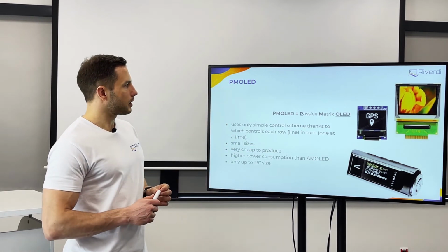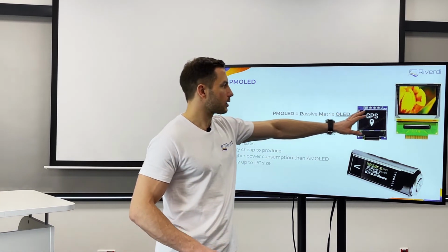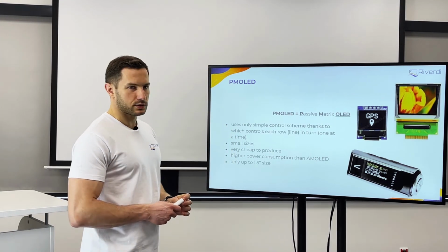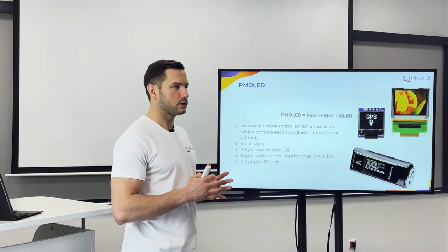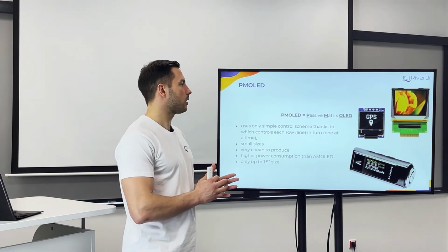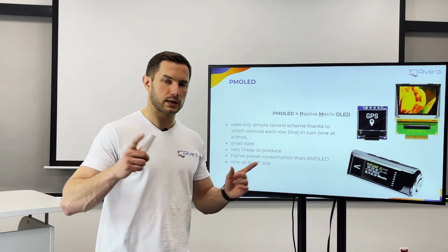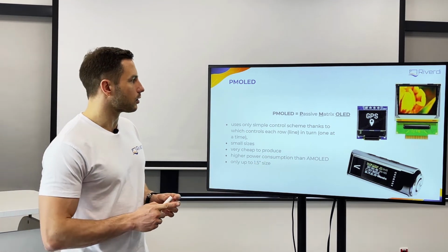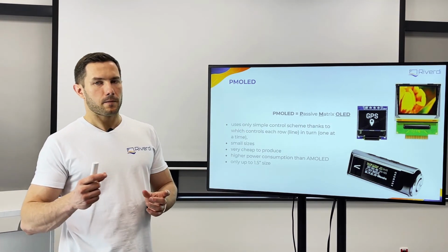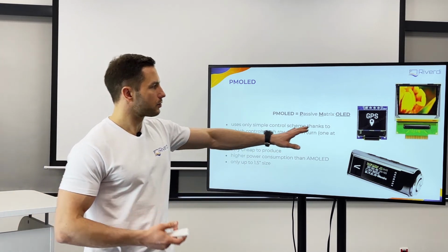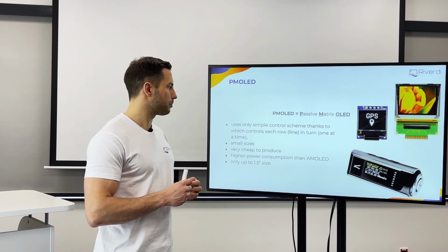And then with passive matrix OLED displays, we can also make full color displays. Of course, no color filter, as I mentioned, we have color pixels there, but they are small. Yes, so limitation here is like with STN displays, we cannot make large displays because the resistance of the lines will be too high, and we will see big differences in the contrast and in the brightness, depending on which pixel we switch on. So we only build passive OLED displays like maybe 1 inch or 2 inch for color, and maybe 3, 4, 5 inch, but they are rather like panoramic displays.